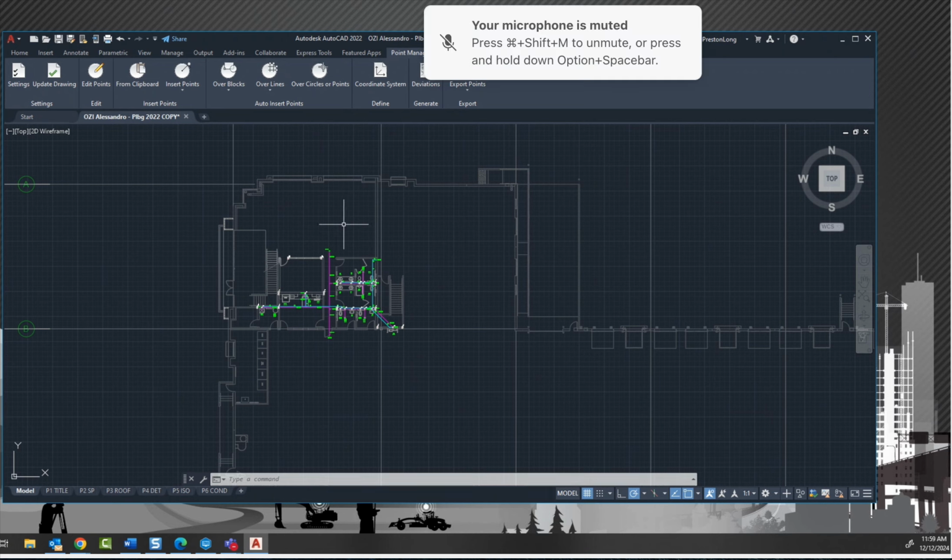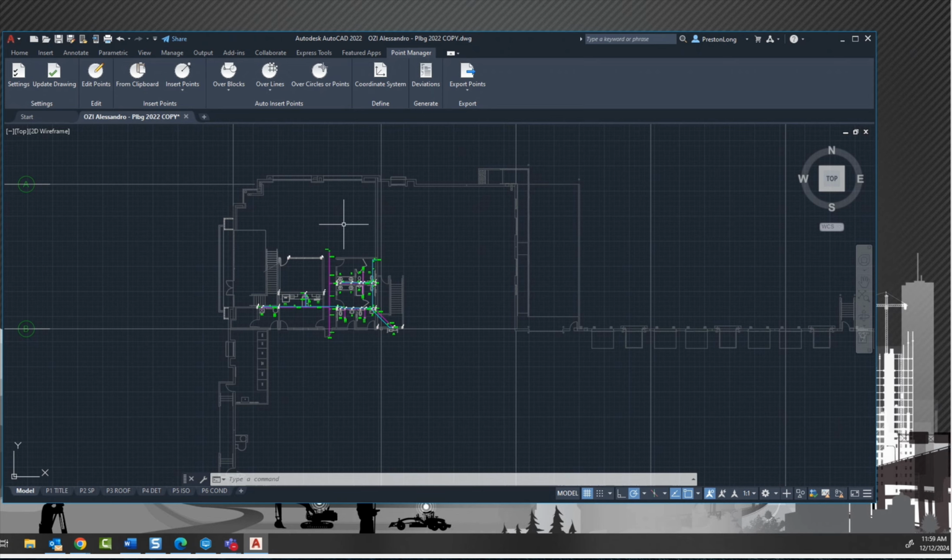So TDL has a few different ways it can set up. It can set up by reading a grid line on the ground, right? Take 2 shots on this grid line, take 2 shots on this grid line. Anything that you're trying to shoot in the field to set up with has to be in the model. Does that make sense? Yeah. So if those 2 things don't match, you're not going to get a very good layout.